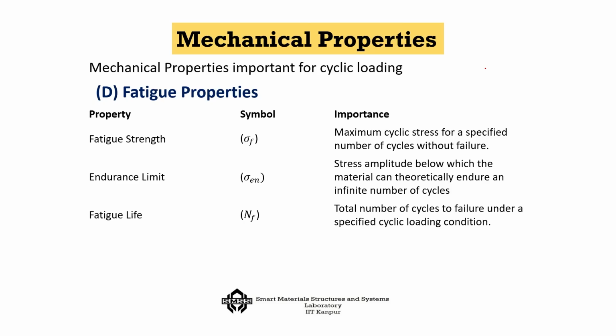So, every time an aircraft flies in the sky and comes back, there is a high pressure to low pressure cycle that operates. Now, this pressure cycle can create a fatigue, and we will call it low cycle fatigue. When we discuss fatigue, I will talk more about these things.